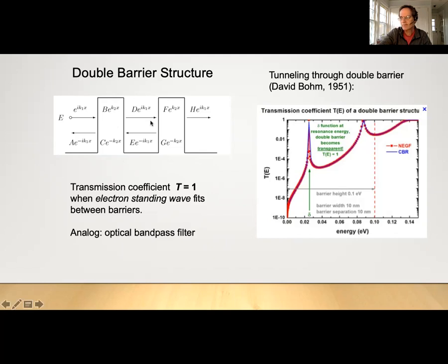In fact, it's the point at which the energy, well, imagine between these walls, you can have a confined state, because this is a quantum well, and the electron confinement would lead to an energy state or a subband with a minimum energy, perhaps right here. And when the energy of the electrons that would tunnel through this barrier equals the energy of that confined state, then tunneling can be very efficient.